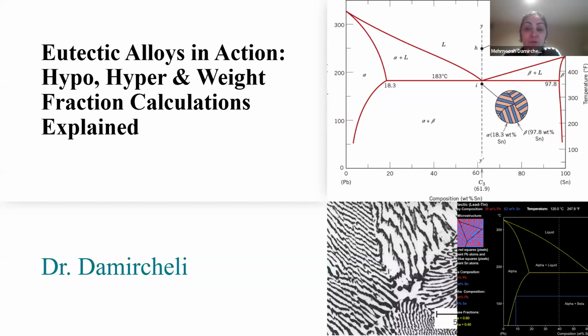Eutectic alloys are so crucial in applications such as soldering, casting, designing alloys with precise melting points and strong uniform macrostructure. So understanding eutectic compositions allows engineers to achieve enhanced strength, hardness, reliability in industrial and structural material.